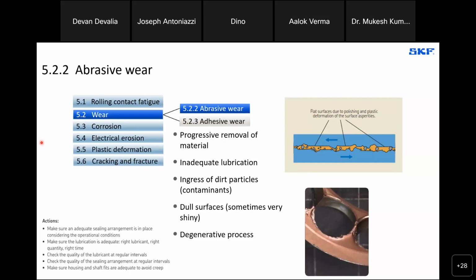There are certain conditions, depending on how hard the mineral contaminant is and the size of it, where we end up with what's called polished wear. So you end up with a really mirror-like polished surface in the bearing. Some folks who may not be familiar with what a brand new bearing looks like may think there are no issues and no problems because it's really nice and shiny, when in truth it's actually damaged. The honing marks have been worn away, and you have this polished surface.